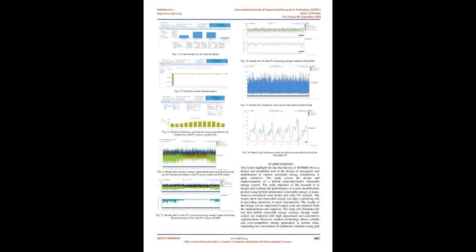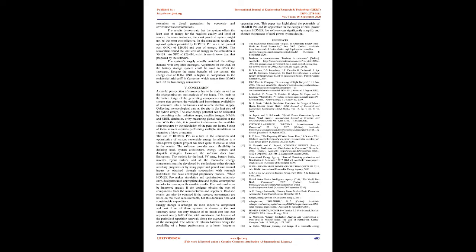The hydropower is operated at rated capacity at all times to provide frequency and voltage stability and improve on system components and configuration. System efficiency. The solar PV system is used to balance the supply. At peak load periods, the storage system comes in to support generation. During periods of low demand, excess generation from the hydropower is used to charge the storage systems. The stored energy can then be used to provide energy during periods of high demand.